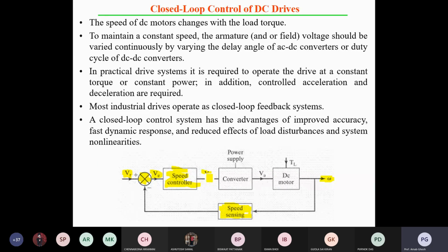It may be a square wave or a triangular wave, like in a power electronic circuit. If the control signal is compared with a triangular wave, you get a PWM. That PWM feeds the switches of the power circuit.